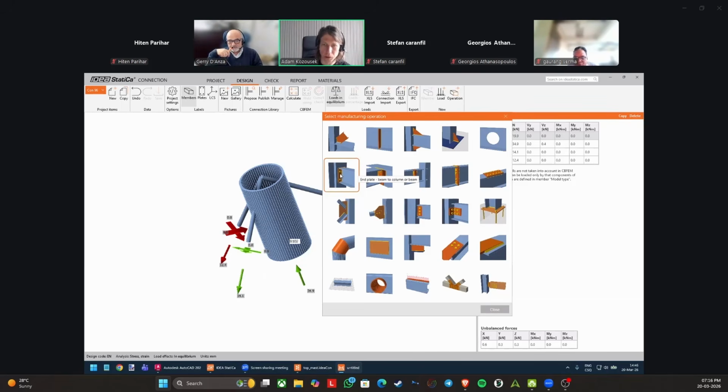So with one click you create the plate, the bolts, the welds, the cuts, and everything. So that speeds up the design process. Or if you like, you have here the list of the general operations, and these actually do just one action, like you create one plate, or you create one bolt, or you perform a cut of plate, something like that, right? So I'll show you how to use them to do our design.